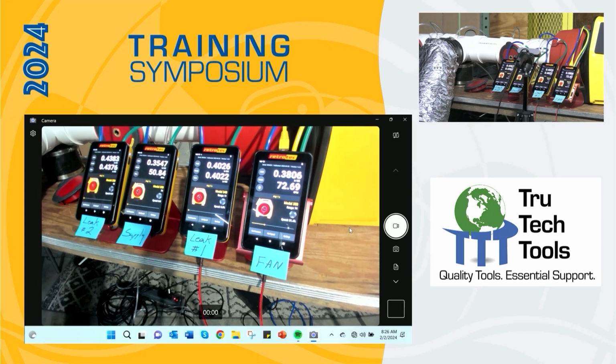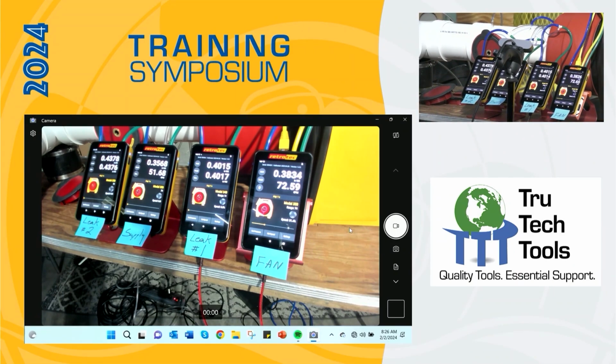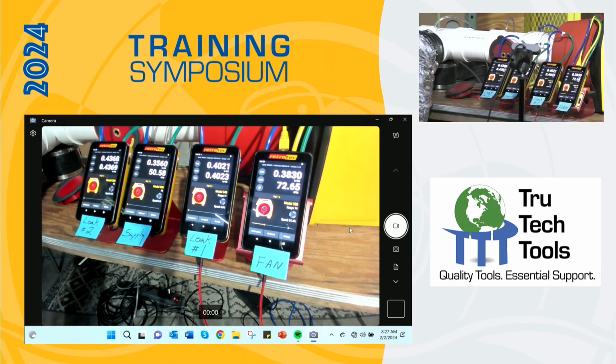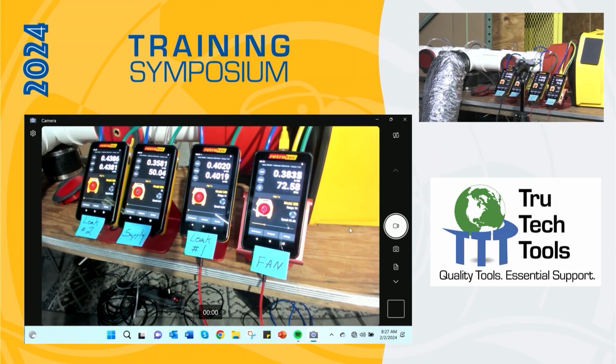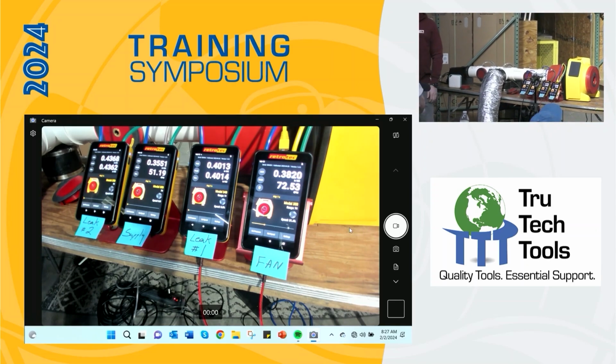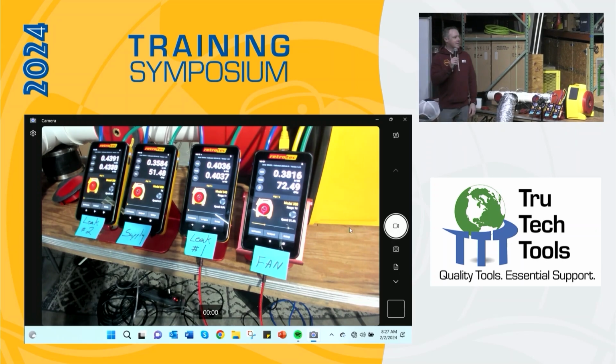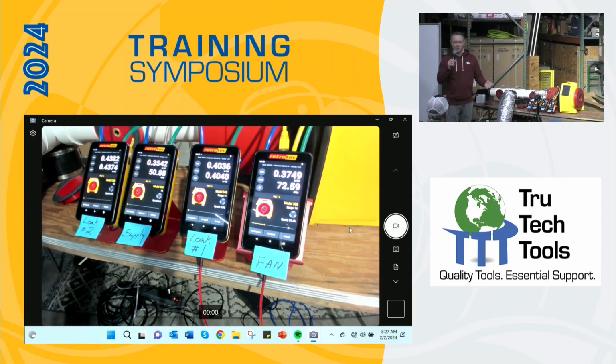Anybody notice anything that kind of happened to some of these numbers? They all changed. So duct leaks are a pressure relief. If you ever measure static pressure on a leaky duct system, and then you go in and do a good job air sealing that system, what's likely going to happen to your static pressure? It's going to go back up. So it's important to measure that again after you change the behavior of that duct system. Again, we're sealing up holes, so now that air is going to behave differently in there, and it's going to make that pressure go up.